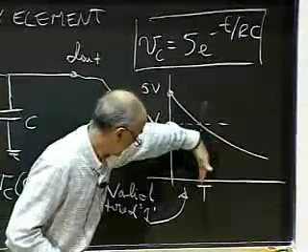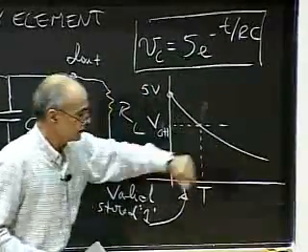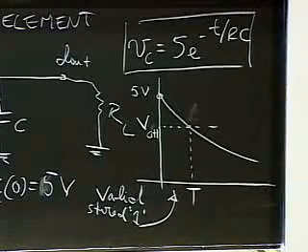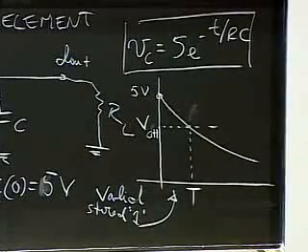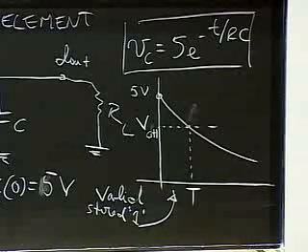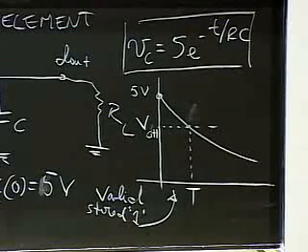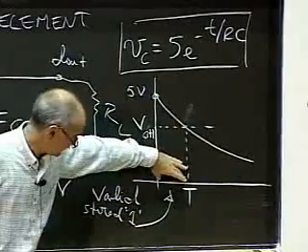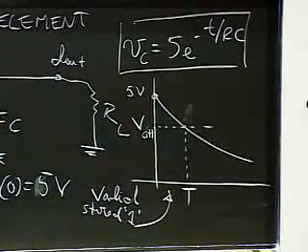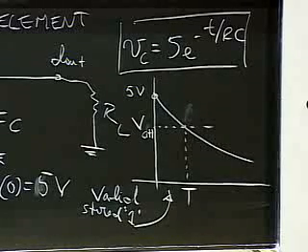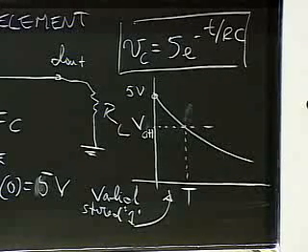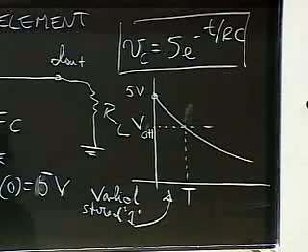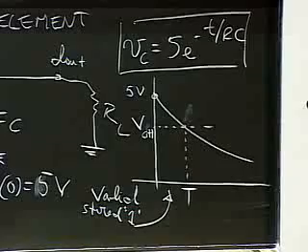Because once I go beyond capital T here, I've crossed the legal limit for threshold for discriminating a high output, and from then on the output is no longer valid. So this memory is good, provided time is less than capital T. Okay, so it is not a case in which the capacitor can hold charge forever.